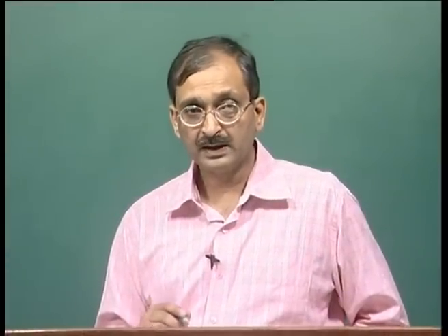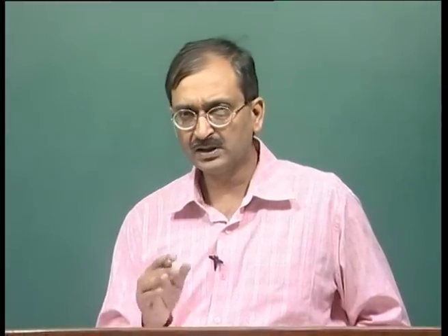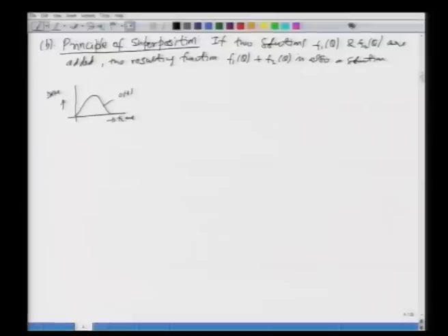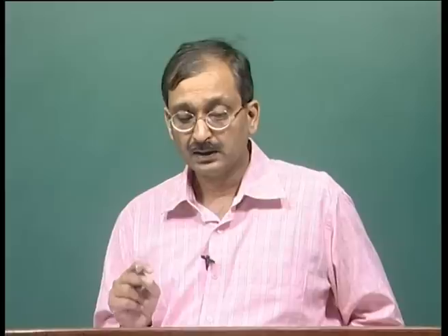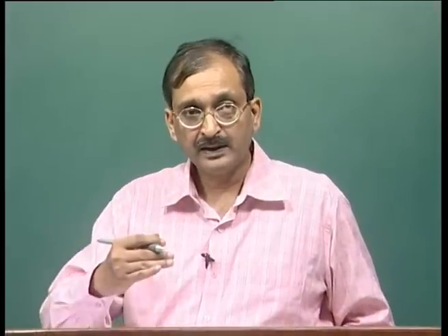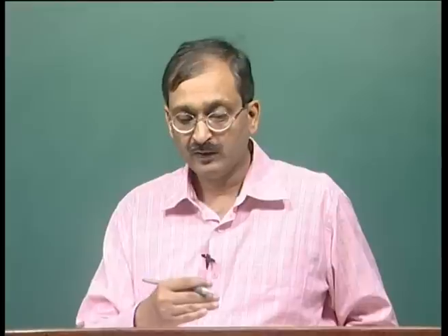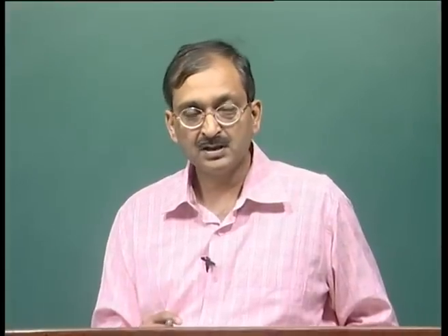Now, if we want to find the direct runoff hydrograph due to x centimeter of rainfall, or 2.3 centimeters of rainfall, what do we do? We use the principle of proportionality and multiply all the ordinates of the unit hydrograph by x, without making any changes with respect to time.